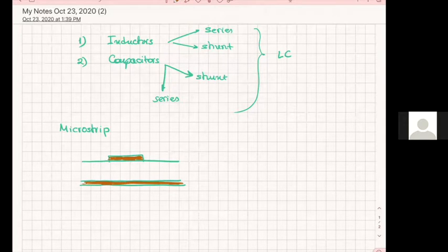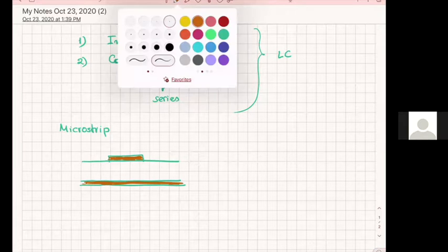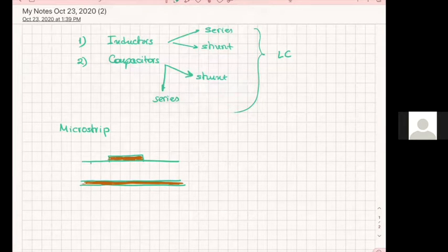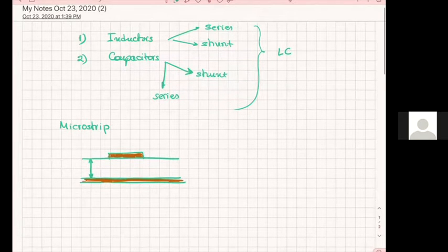The dielectric has a thickness, and how much did I give you, 100 microns or more, or 200 for this homework? 500 microns, I think. Okay, so H is 500 microns. And W, I did not give you W because I gave you epsilon, and that was 3 point something? You gave it as 4. 4, okay.